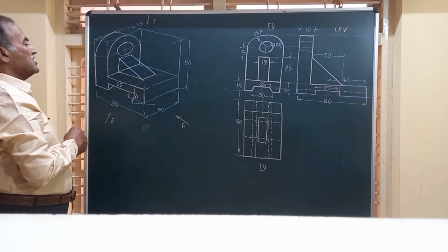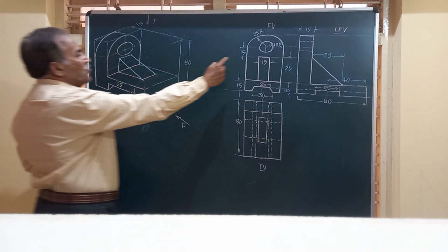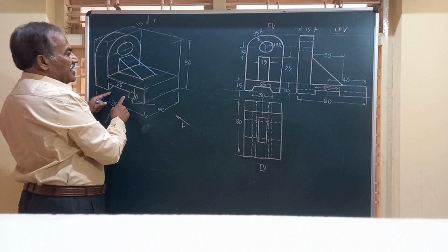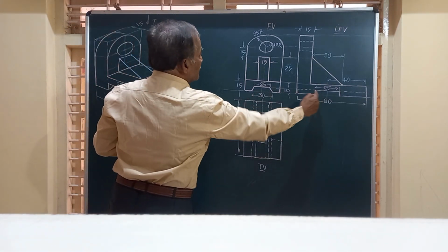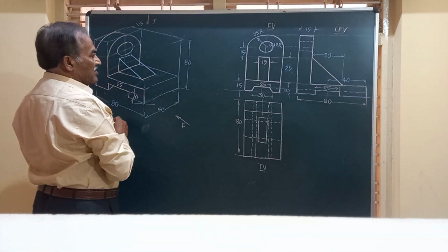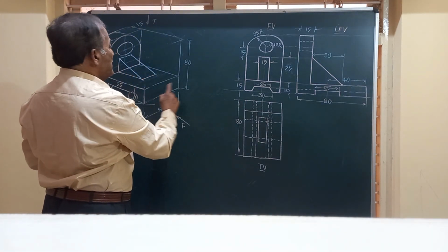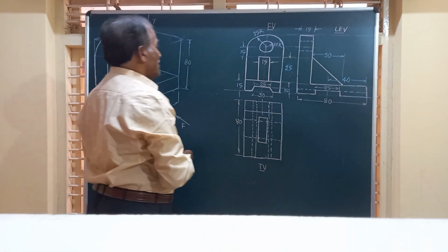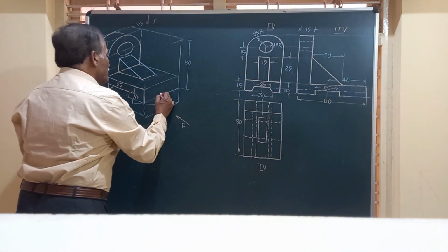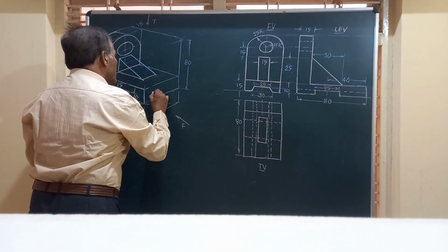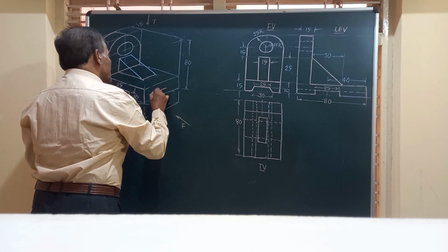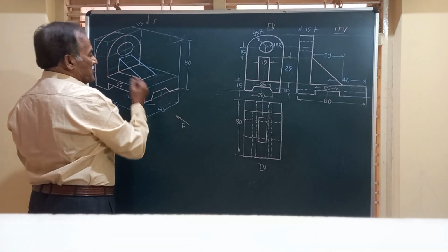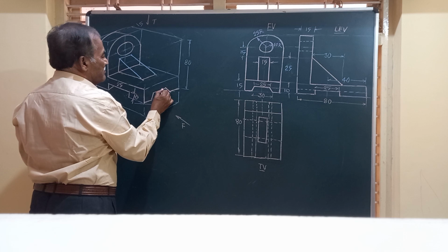And friends, here you can see we have marked this slot here, the semicircular end at the extreme end, and you have this rectangular slot in the print. Not rectangular, it is supposed, here it's going to be a dovetail. This is called a dovetail slot or a trapezoidal slot. Exactly in the center, friends, we can locate the center of this line and mark here at a height what is called a dovetail cutout, and we can draw a line parallel to this from here, friends.